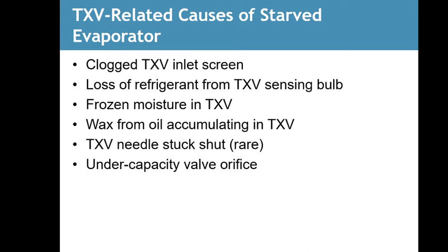Related causes of a starved evaporator: clogging TXV inlet screen, loss of refrigerant from TXV sensing bulb, frozen moisture in TXV, wax from oil accumulating on TXV, needle stuck shut, and that's rare, under capacity valve orifice.